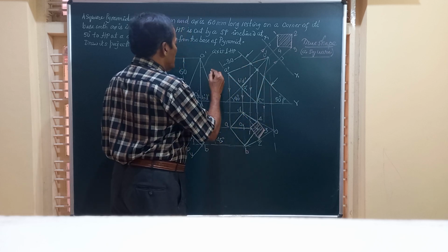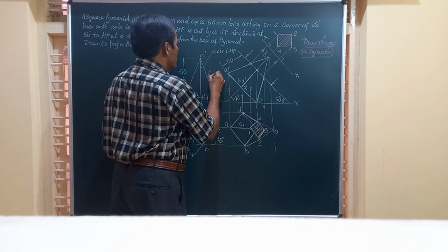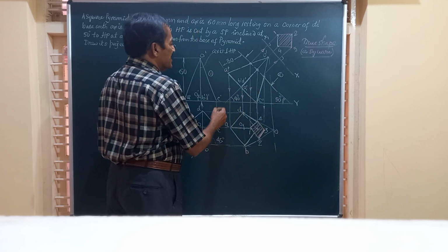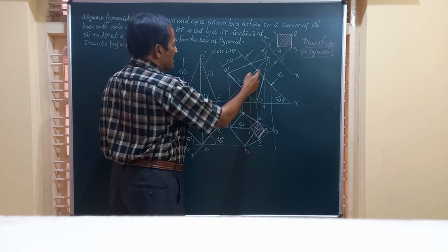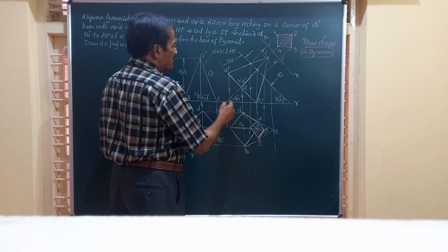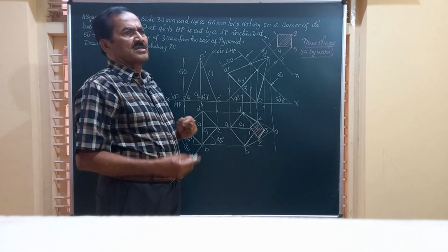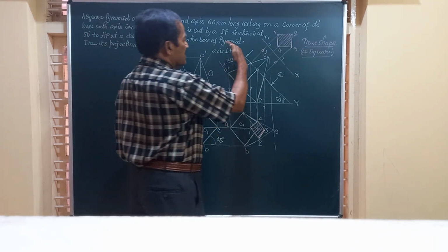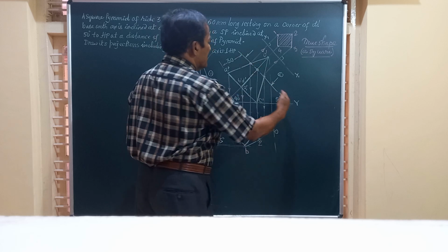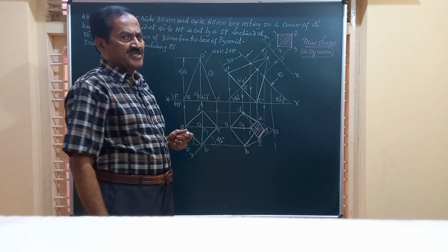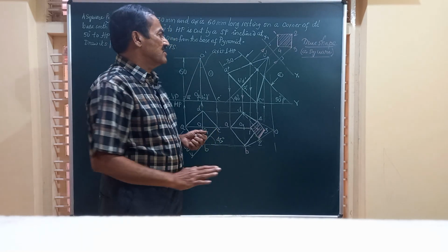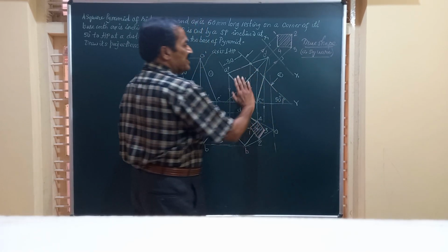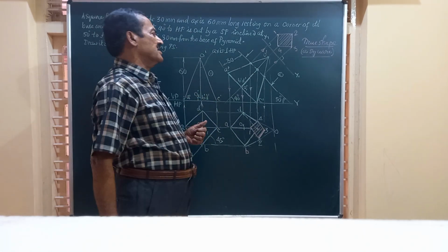So friends, I am going to obtain this figure 1 here as figure number 2. Only the difference is that the axis was perpendicular. Now it is made at an angle of 40 degrees to HP. Now the section plane is cutting this solid in this position, and this section plane is inclined at 50 degrees to HP. Friends, generally when the object is inclined to the right, the section plane is inclined to the left. We take it as inclined to the left.